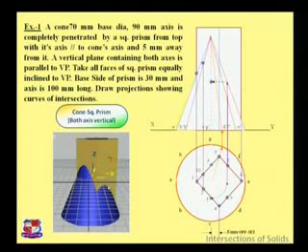Now we have to worry about the rest of these curves, and for this curve we identify this point as well as this point. So for that, mark the points over here, 1, 2 and 3. This is the point of intersection of this prism and cone. This apex point is here, the uppermost point, and this is the point. And then name all these points transferred from top view. So 1 dash, 2 dash, 3 dash, 4 dash, 5 dash, and so on. Respectively name all these points 1 dash, 2 dash, 3 dash, 4 dash, 5 dash, 6 dash onwards.